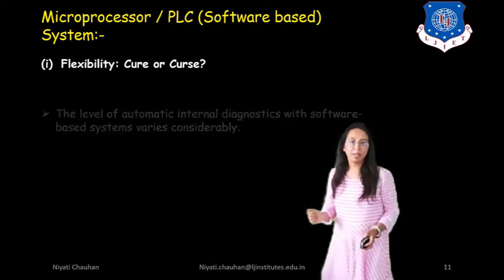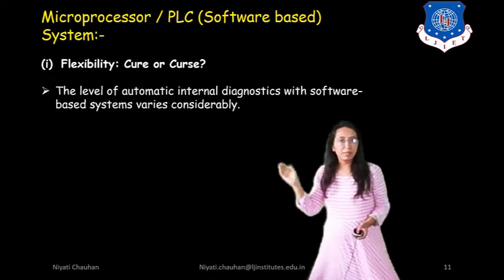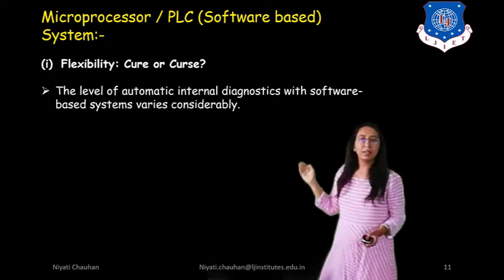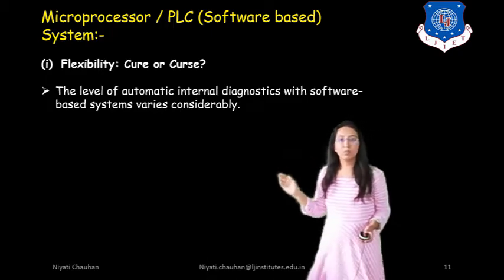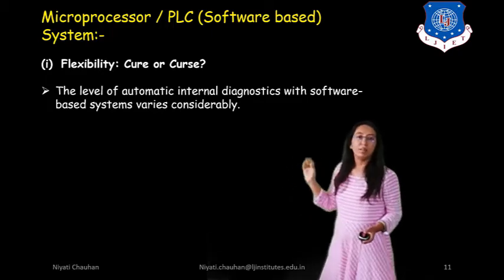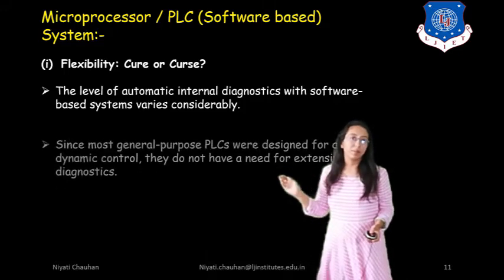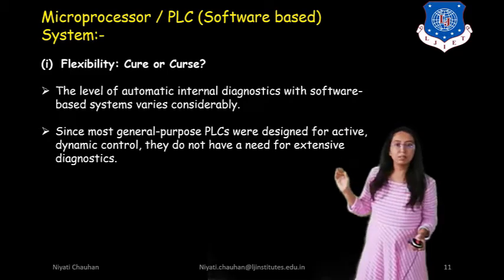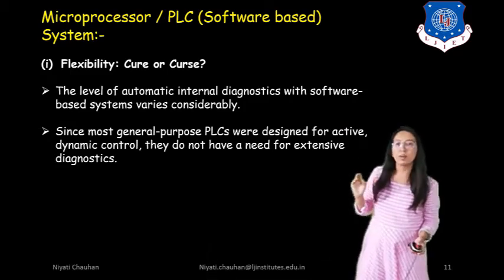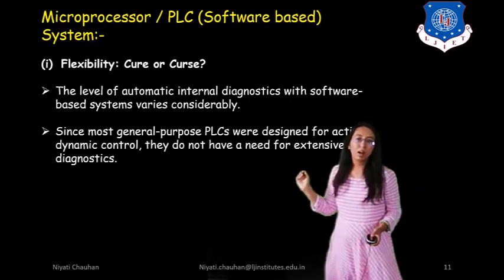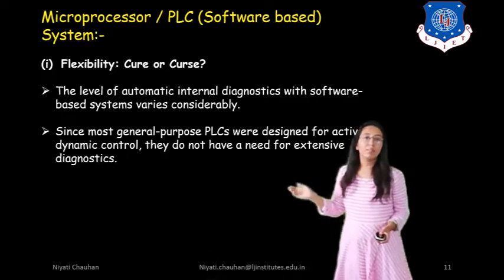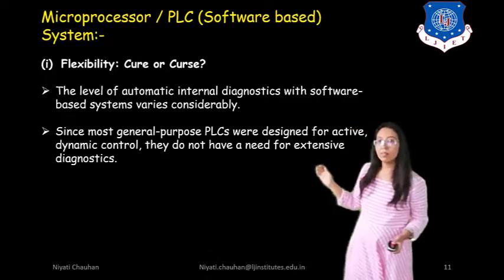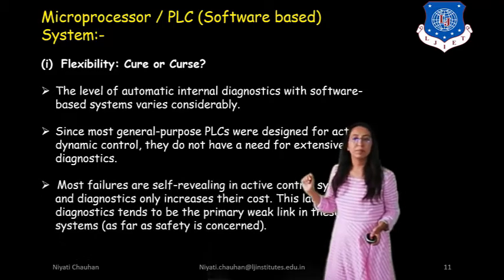Next, the level of automatic internal diagnostics with software-based systems varies considerably. Since most general purpose PLCs were designed for active dynamic control, they do not have a need for extensive diagnostics.